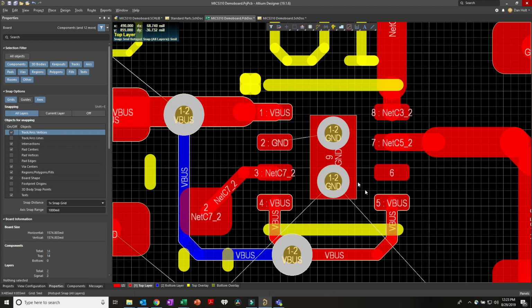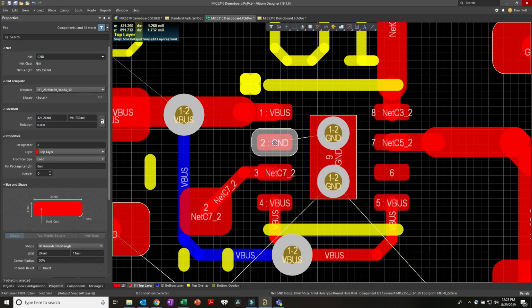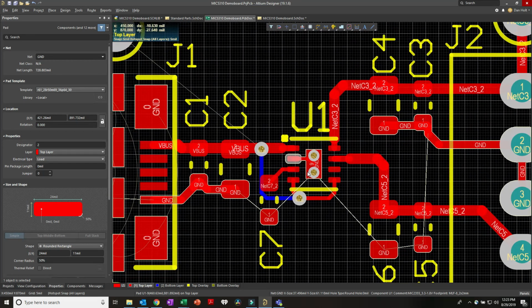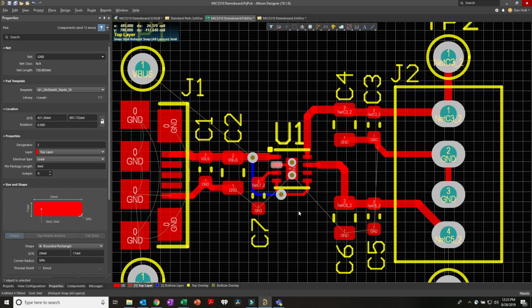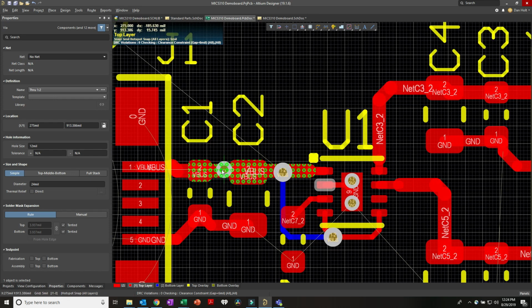and press Tab to hit properties. Well, this is properties for the whole thing. Okay, there we go, properties for just this pin. Designator is 9. The name, we'll call it EP, exposed pad. And we'll call it a power pad. Okay, let's stick that right there. And then we're going to say Tools, Update Schematics. Very good.